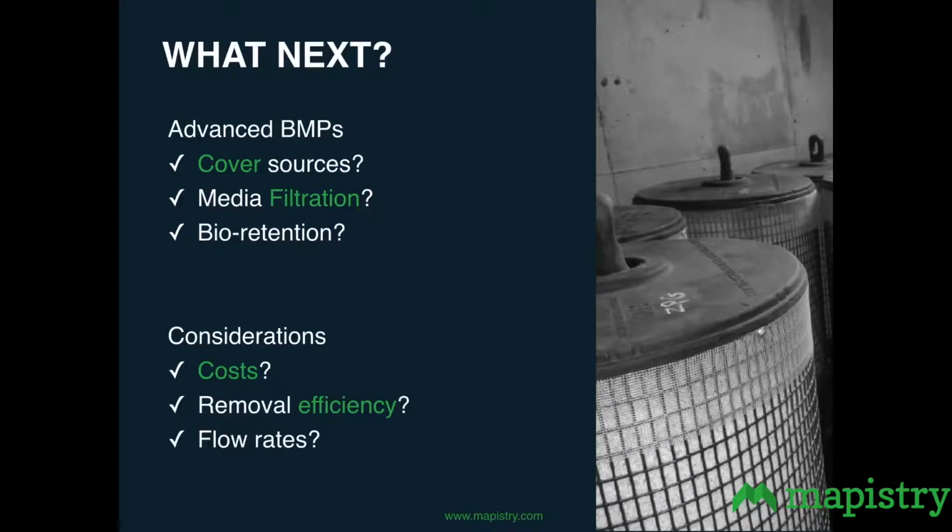Bioretention, you don't want to discharge stormwater if possible, so whatever you can do to infiltrate it, whether it's an infiltration gallery, a sand filter in the ground, a bioretention cell in the ground, whatever you can do to put it in the ground temporarily, or just while you're figuring it out, you can always put a temporary sand filter on your site.